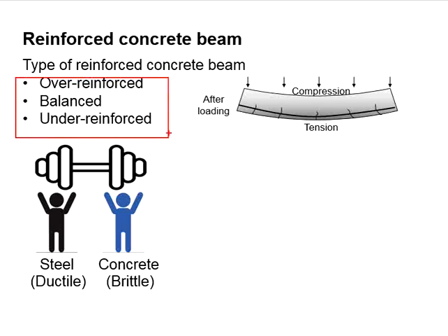As implied by the terminologies here, over-reinforced beam means that you have plenty of reinforcement, surpassing what is necessarily needed. As for the under-reinforced beam, the amount of reinforcement is insufficient as compared to what is required. As for the balanced reinforced beam, that means the amount of reinforcement is at the break-even point, where the amount provided is just nice to meet the capacity of the concrete.